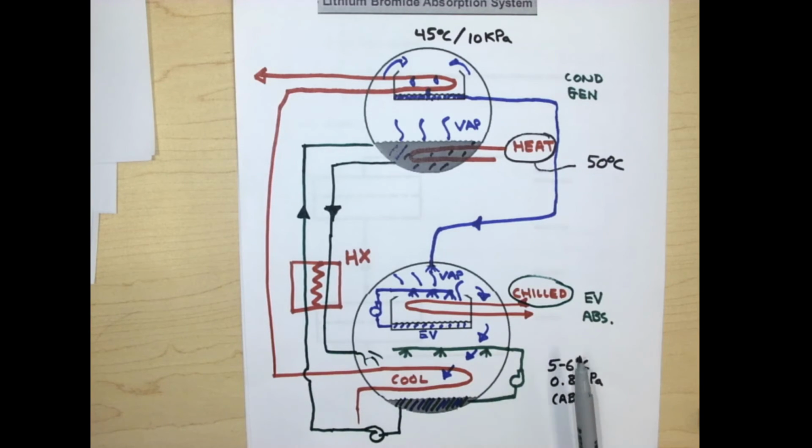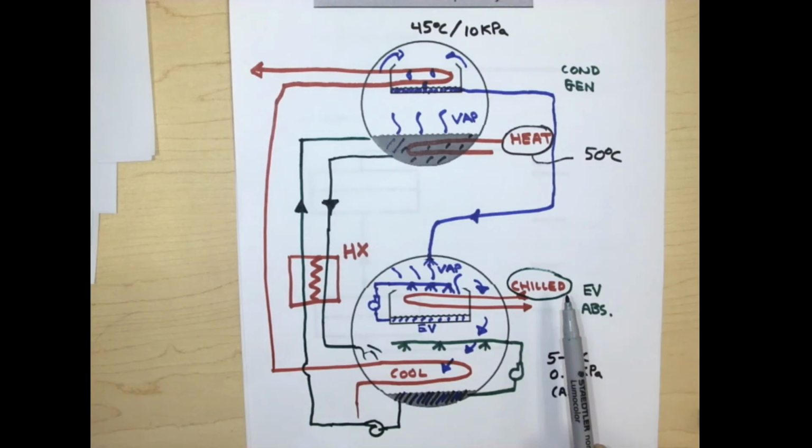So our chilled system, really we could tie into it with any device anywhere. Okay, so it's not just one central spot where the heat has to be added in. So you may have a number of rooftop units and a continuous flow of cooling water through the building. And maybe some of your rooftop units are absorption units, and maybe some are mechanical refrigeration, compression refrigeration systems.